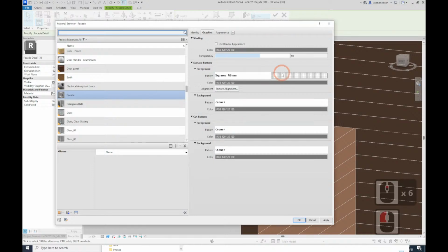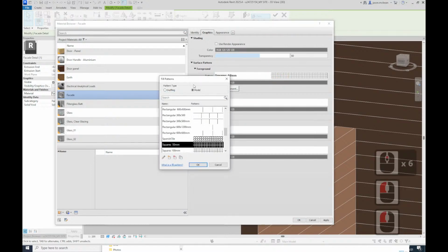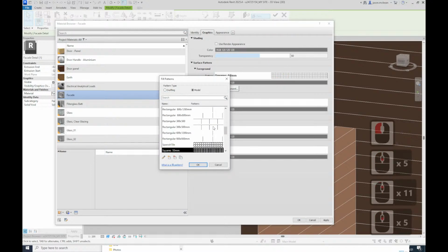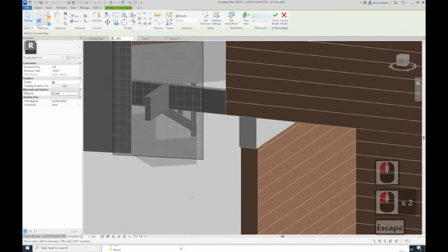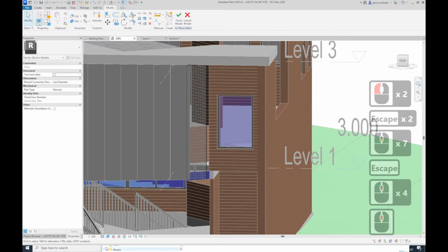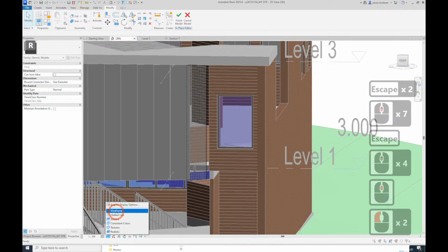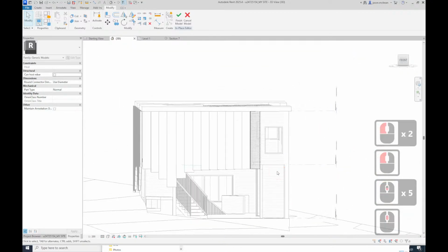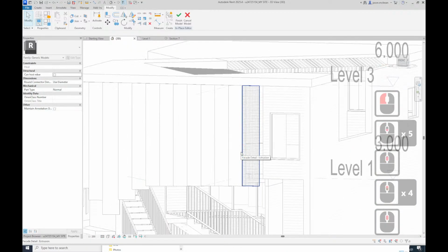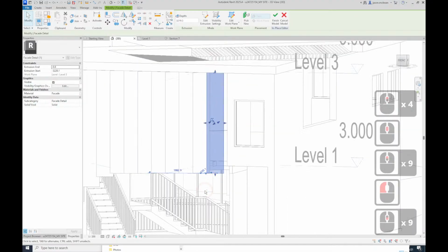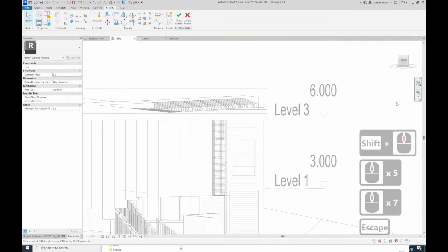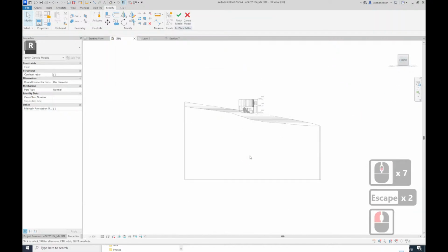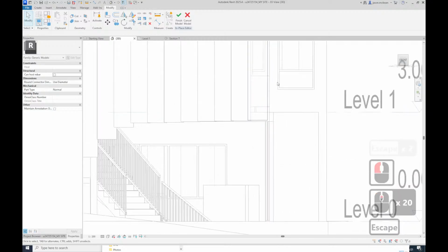But now you have to go and find a hatch pattern that might work with this and a model. It's very difficult to make these hatch patterns. You can get them offline and load them in, but for the exercise and for this workshop, you'll see now what it does. I can now see through. So do you think that hatch pattern would work for the exam and everything? It will. And you can just say it's a perforated steel mesh, and you put a note. Because it's that materiality you define. Because if you had to go and model that little hatch pattern, you'd be here for the next month.